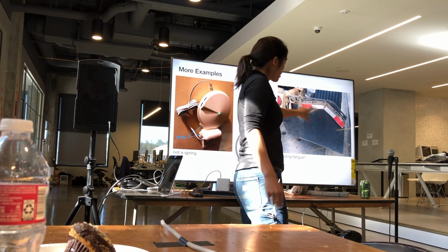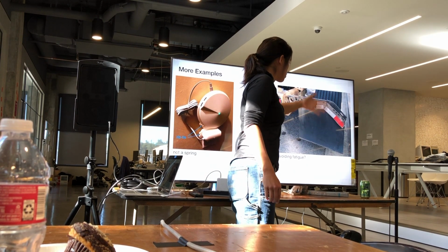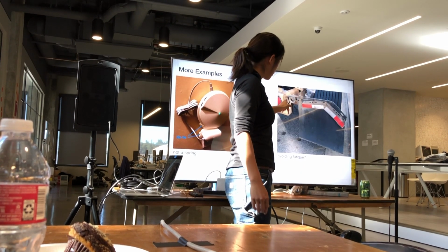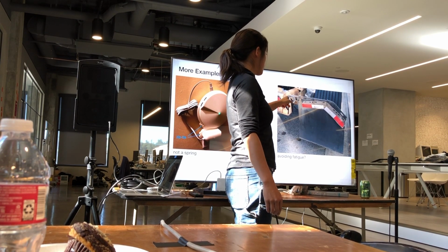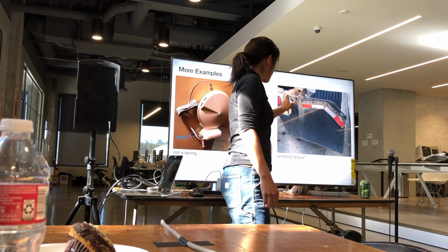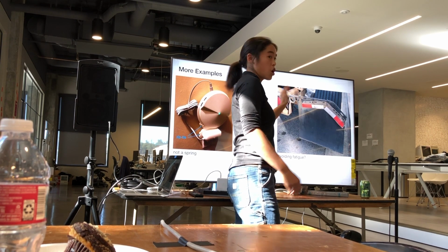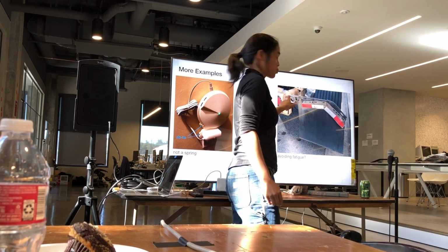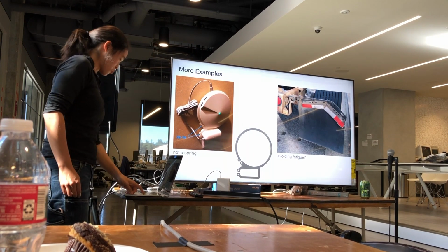This one I saw yesterday, and I just really liked it. This is the mud guard on a big semi-truck, and I imagine this thing is quite heavy as the truck is driving along, so there's probably a lot of stress in this joint here, and they're probably trying to avoid fatigue happening on this particular joint. By putting this structure in, they're essentially spreading the deformation along a much longer length of material, so the percentage strain across all that material is much less than if it only had that little joint there. So I just think it's a cool use.